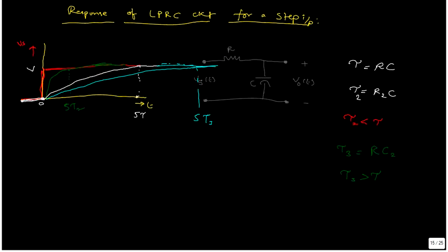This all depends on only one important point: when a constant voltage or a step signal is applied to an RC circuit, the voltage across the capacitor starts charging exponentially and it reaches the final value in a minimum of 5 time constants. Based on this, we can draw the output waveform for the given time constants, and we can also calculate the voltage at any point.